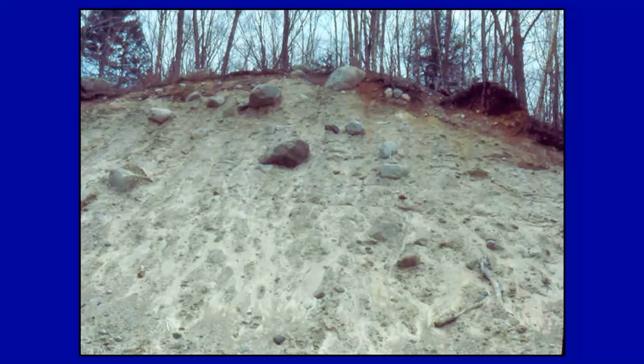Here we have glacial till, which drillers call hardpan. This is material which was laid down beneath the ice. It goes anything from clay particles through silt, sands, and in fact, boulders. Now there are two types of till. If the glacier stagnates and the ice melts down and the material within is just deposited beneath the ice, then in fact it's an ablation till.